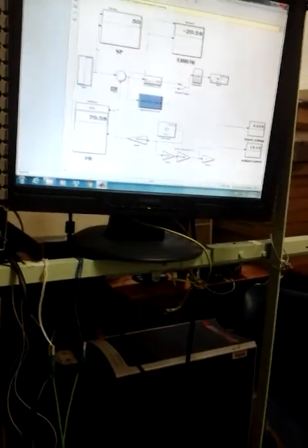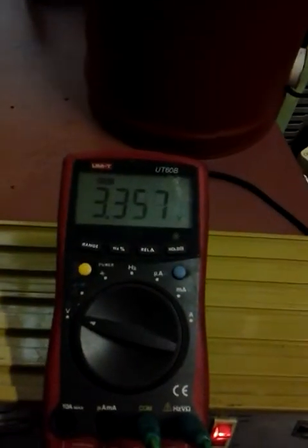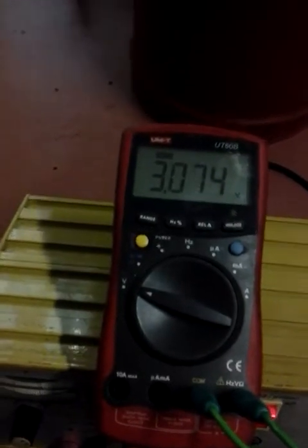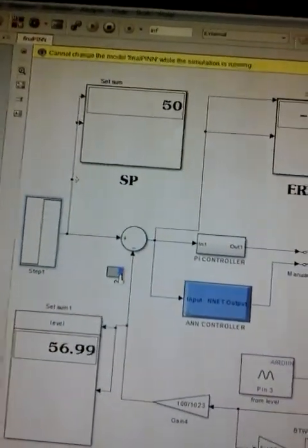So this is a linear process. That's how you can try to get the value. Okay, so if I have to put the set point to 50, I'm expecting a value around 2.5. Let's change to 50% and see. You enter there, you see this value must decrease. It should be around 2.5 volts. I'll observe first here. This is my set point. So I decrease to 50%.